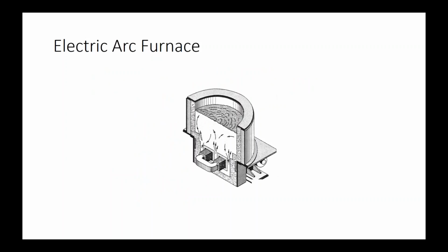Most metal handling facilities or metal producing facilities use electric arc furnaces these days. Here's a cross-section of a typical, but not only, type of electric arc furnace. This is a channel furnace. There are others. And in some cases, multiple electric arc furnaces are used. You're pouring from one to fill up a tundish or a holding furnace, and you're melting in others to make sure you have product continuously if you're doing continuous casting. And so we're talking about continuous casting.